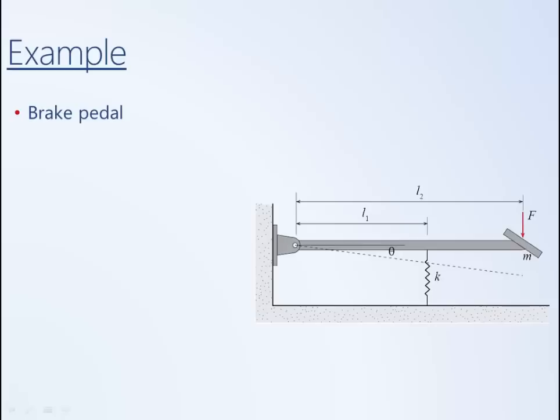With a brake-by-wire system in an electric vehicle, you may want to do braking by running a generator. And so there isn't necessarily a mechanical connection to the brake calipers. And so what you want to do is you want to emulate that feedback. You want to give the driver the same sort of feel. So that's one reason why you may want to model the dynamics of a brake pedal.